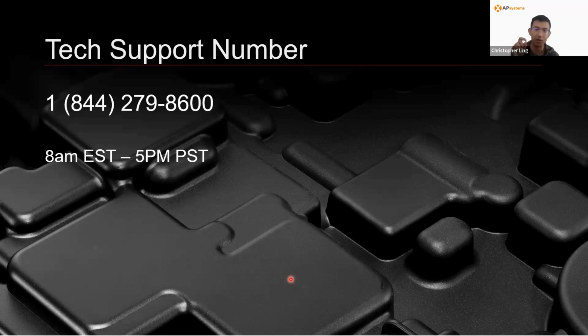You have an ECU-R connected to a Chint meter, and the Chint meter is the interface that allows you to connect CTs to it and to do the export control or monitoring. I generally recommend the ECU-C because it's an easier install. But the Chint meters are revenue grade and NC certified, so they're more accurate. So those are useful for those types of applications.